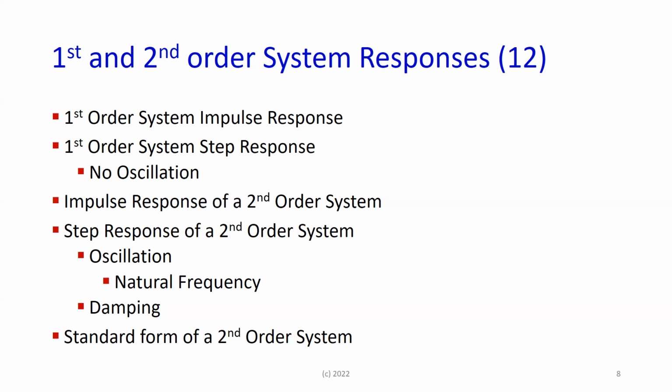You put a step into it, the capacitor will charge. We put a step voltage here. A first order system will try to respond by giving you, again, nothing before, and then something looking like that. It eventually settles at the value of the step input.